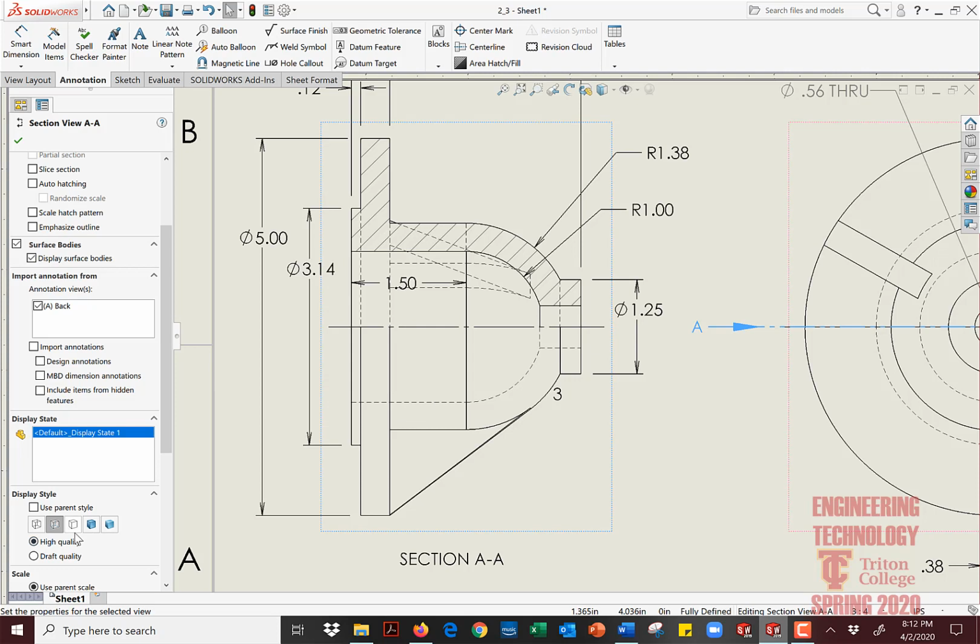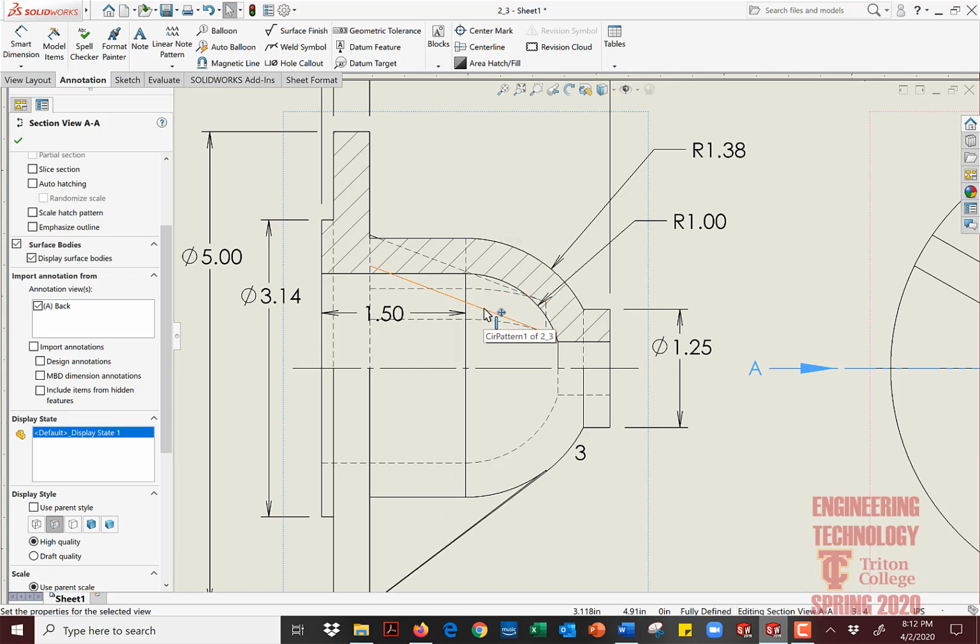This product is not that defined. If you really wanted to do it, because maybe you have a boss who insists on it, the way to do it is you turn your hidden lines on, and then you literally have to surgically turn off visibility for every object that you don't want to see.